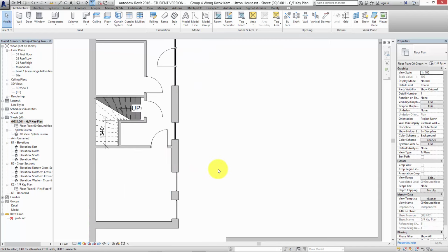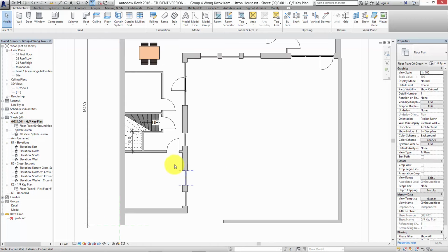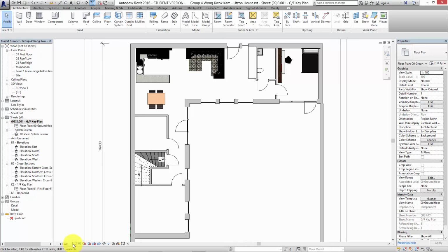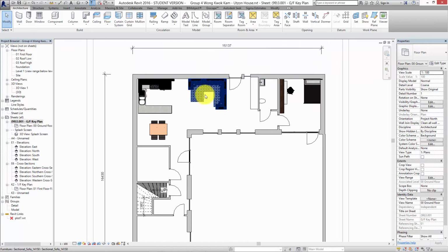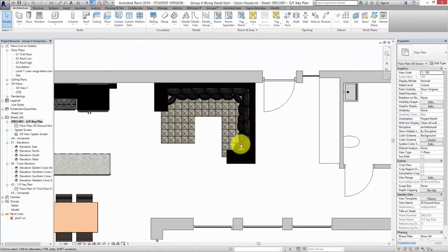So now, when you're showing it to the client, he's not going to go, why does that wall have 3 stripes in it? Because then you're into a whole discussion that you don't want. You want them to think about what their lifestyle is, how they are going to use the place. So it's actually what products you're selling them here. So at this stage I would always keep the detail level to coarse, which will take all the constructional detail out of the wall.